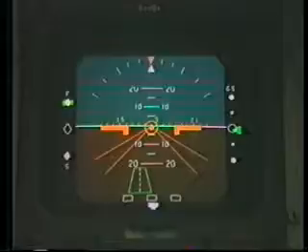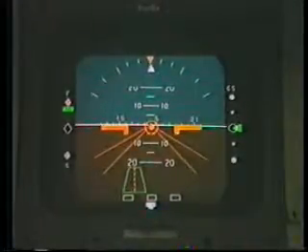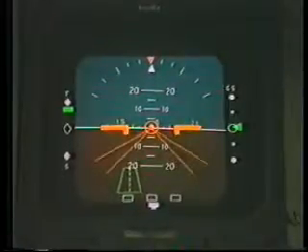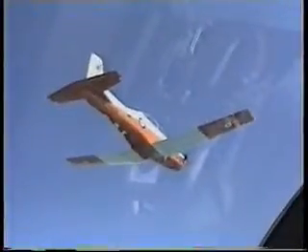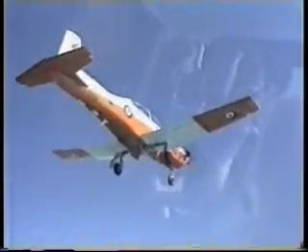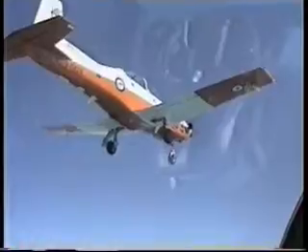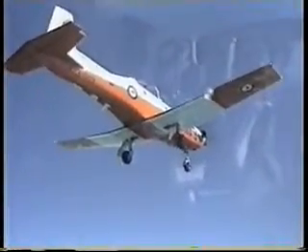On the EADI, notice the runway and the glide slope scale. The runway symbol is very sensitive and is useful for identifying trends. Complete the checks and then concentrate on accurate flying. Only small changes are required on finals. Don't over-control.